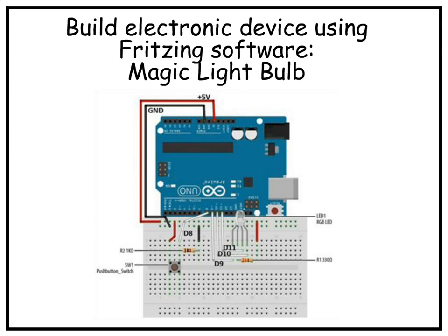So we got all our parts. We got the block diagram. We have our schematic. So this is a good example of the Fritzing software. The schematic that we looked at a couple slides earlier came from the Fritzing software as well. But when you first start Fritzing, it has what's called a breadboard view, and that's what this is. This is the actual breadboard. And then what we do is we have our parts list. So we start going into this little virtual electronics bin of cool components,